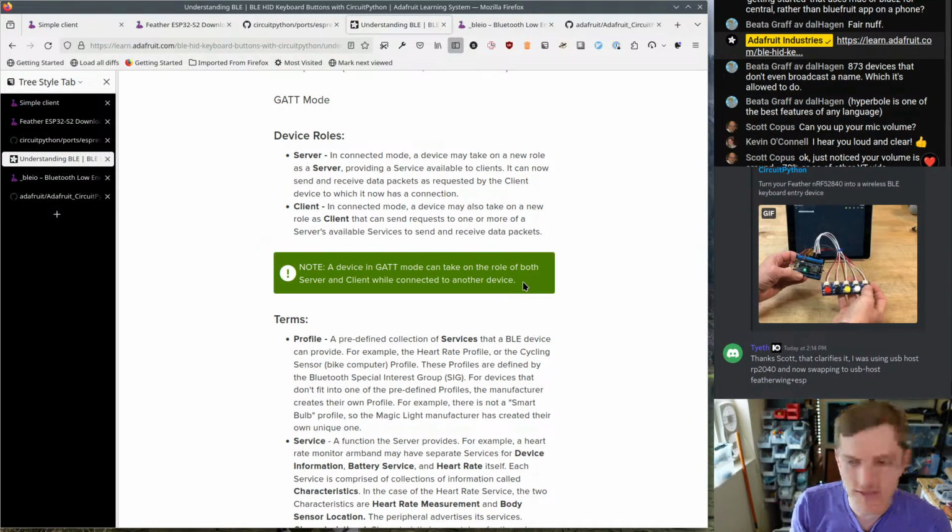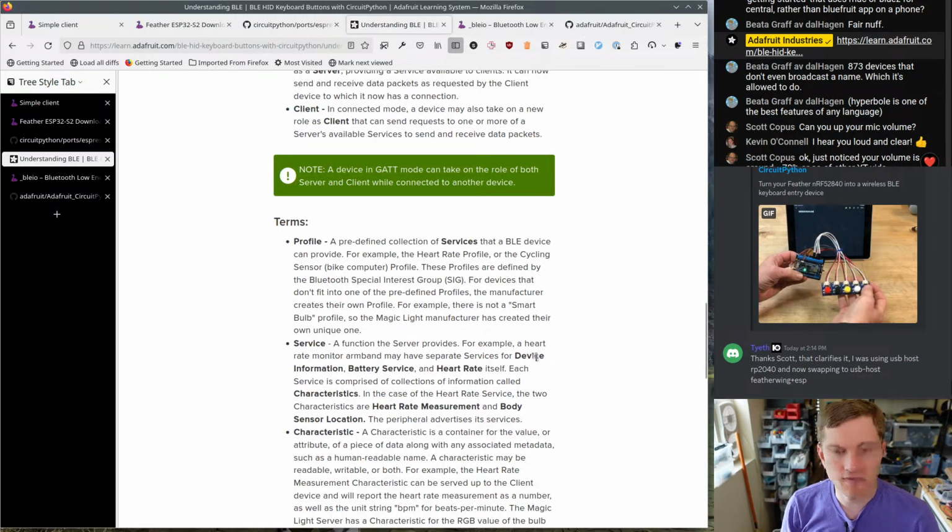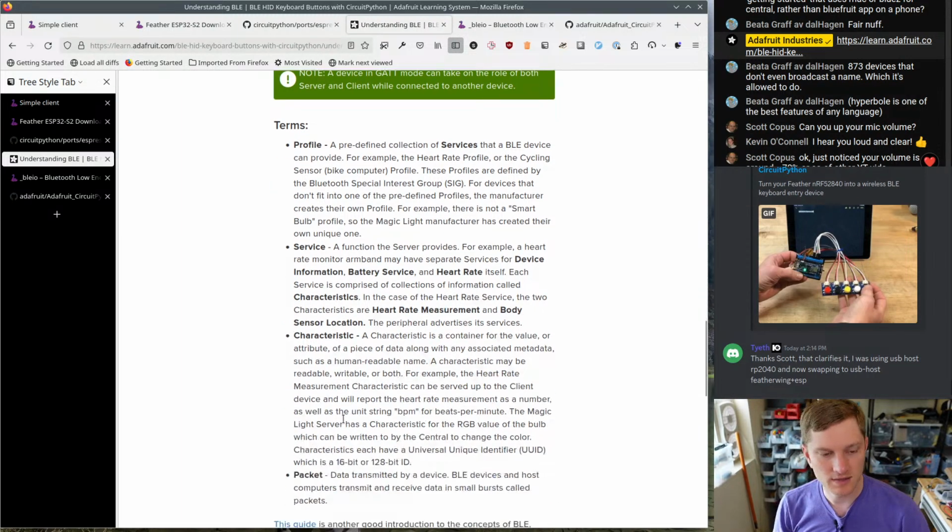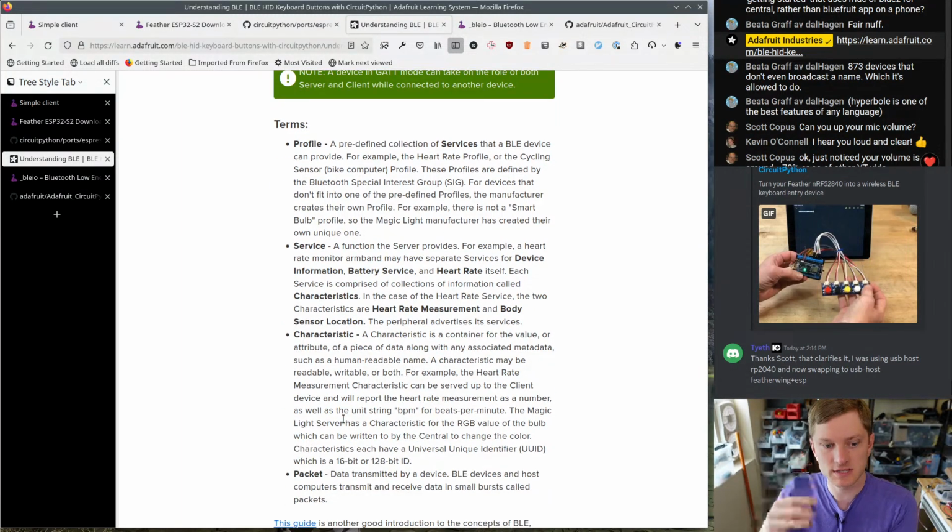So a service is, and sometimes I mix server and service, but a service defines data. So this has examples: you can have device information service, you can have heart rate service, and then talking about USB keyboards, you can also have a human interface device service. A service is made up of characteristics. So a service is a collection of characteristics, and then characteristics can actually have descriptors to hold meta information about characteristics.